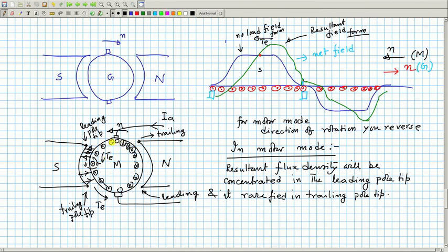Therefore, because of this cross and dot there will be a flux here, because this portion of the conductors has not been nullified. So, the compensating winding at best can compensate maybe 70%, if this length divided by this length is 0.7, then 70% of this armature MMF can be compensated. However, this cross and this dot will give a current here, flux there, and it causes problems.